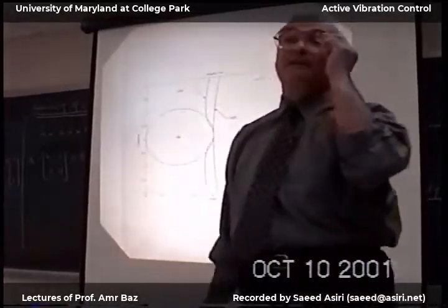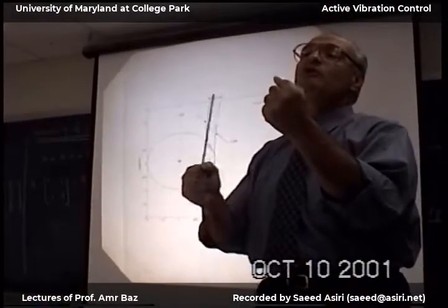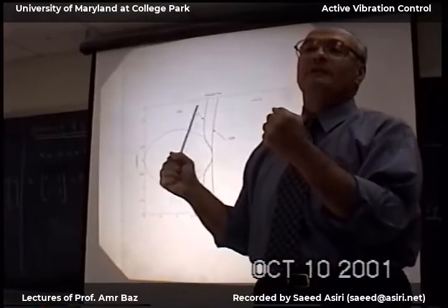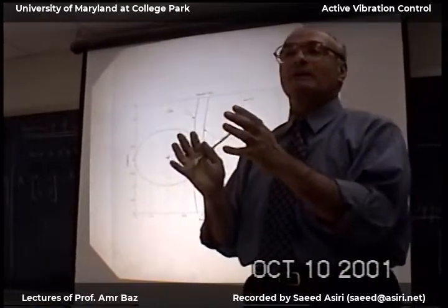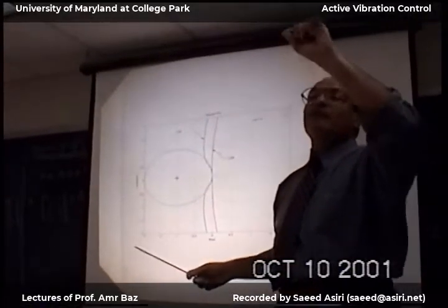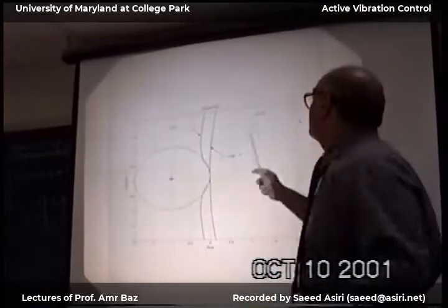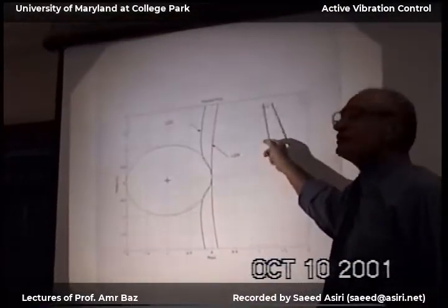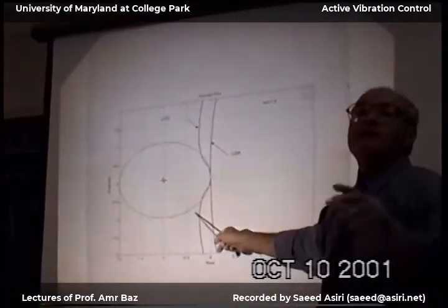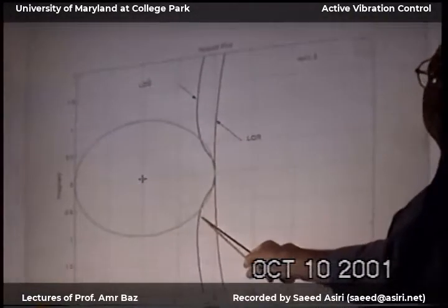So again, in this example, because we have a single spring mass system, you need to do a lot of damage to it to make it unstable, okay? Because it has good damping. This system has damping of 0.5, so it's very high damping, and it's a single degree of freedom. So I had to change 50% to start seeing an instability problem or loss of the phase margin.